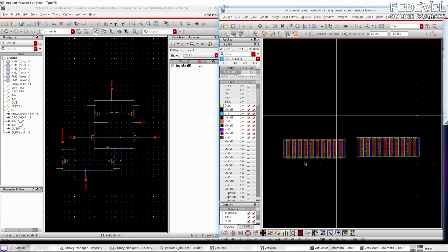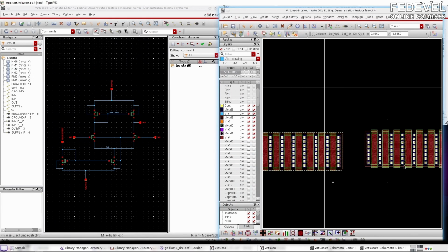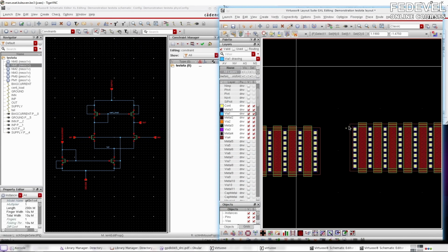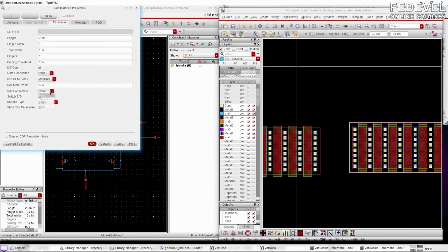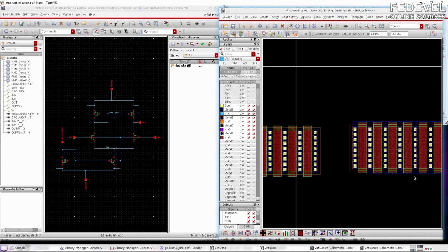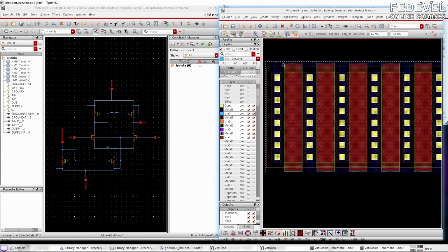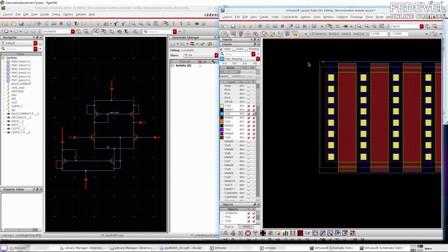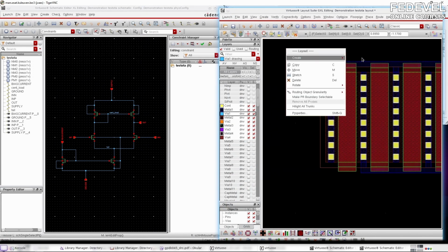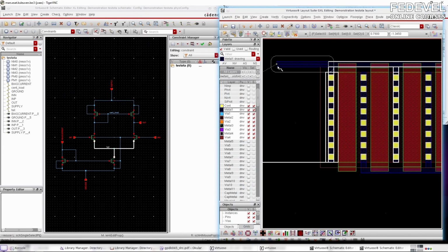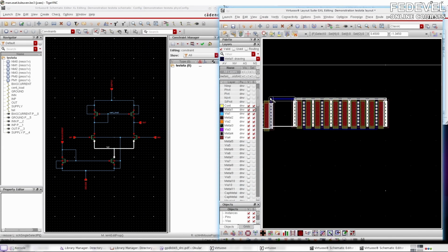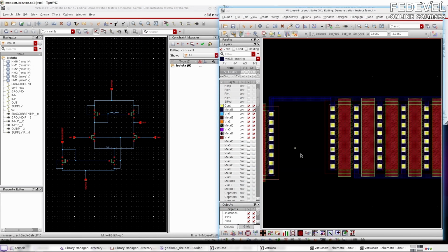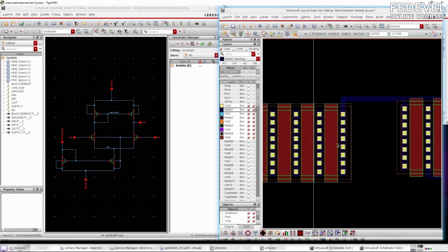And then you need to connect the source, and so on? Exactly. I can even tell the software to please already make some connections for me. In blue, in metal 1, it's placed these connections. And if I then start routing, voila, it tells me you have to connect this there. And now that's connected. So I would do these connections in all of these metal layers.